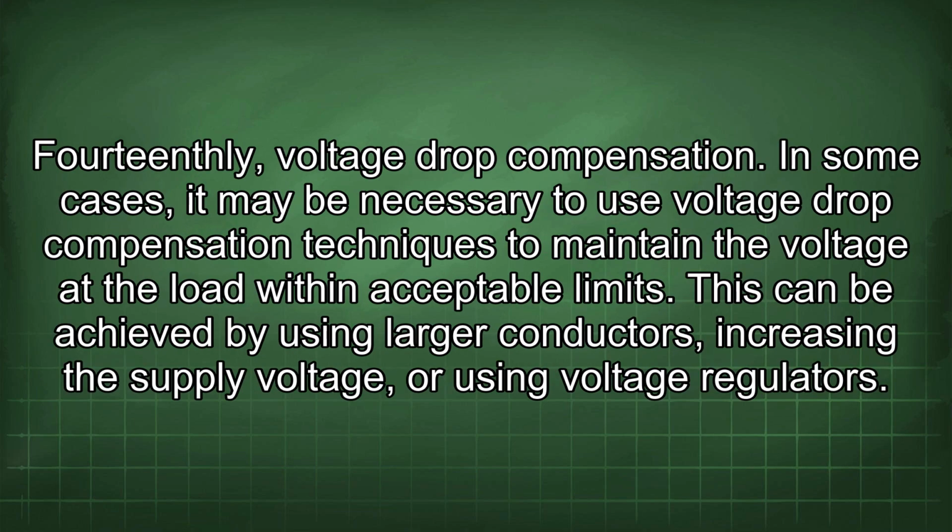14thly, voltage drop compensation. In some cases, it may be necessary to use voltage drop compensation techniques to maintain the voltage at the load within acceptable limits. This can be achieved by using larger conductors, increasing the supply voltage, or using voltage regulators.